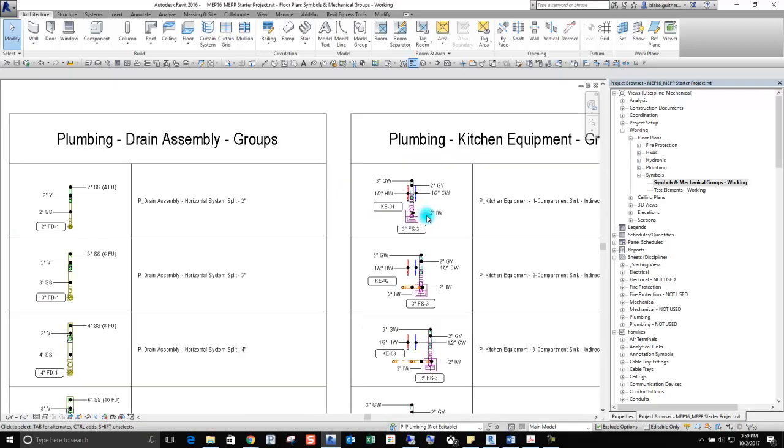Once again, these are essentially an initial set of families placed that you ungroup when you're done. This is a different philosophy than using groups for a high-rise building that has a core area or bathrooms that are stacked all the way up. That's another good way to use groups. This is a little different though. This is just an initial set of families placed and connected so that you can save time modeling down the road.